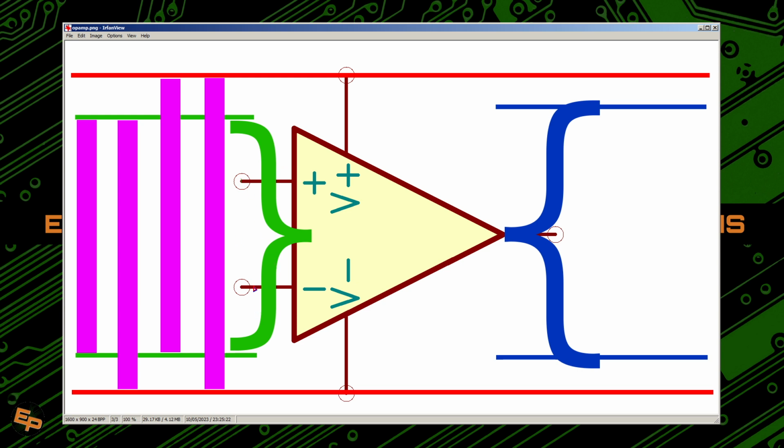Well, the idea is that the voltage that we must apply on either of the inputs must fall within a certain range of acceptable voltages, and the output that the op-amp is going to give us will also be within a certain range that the op-amp is able to provide on its output, right?